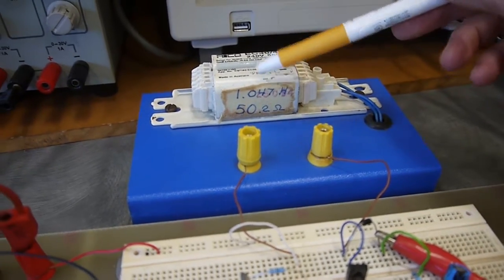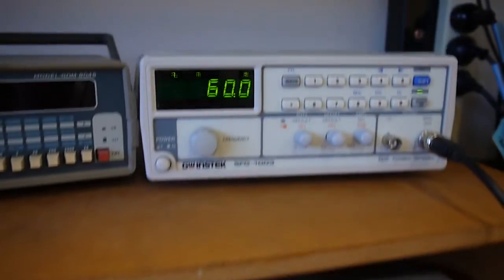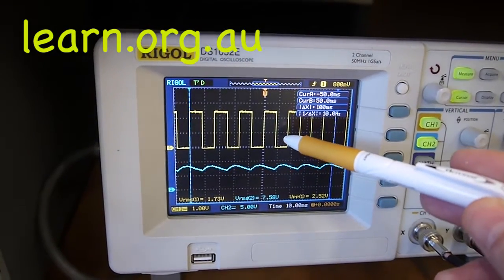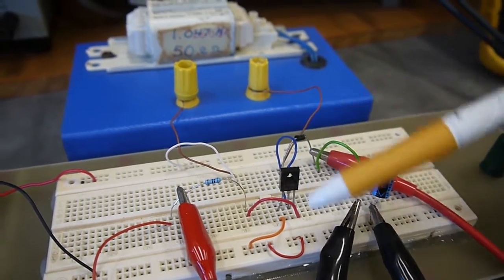Therefore the magnetic field builds up around the inductor, and then using the square wave from the function generator, you can see it here on the oscilloscope, we're switching the base on that transistor, which is causing the transistor to turn on and off quite rapidly.